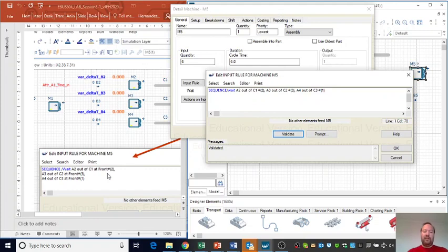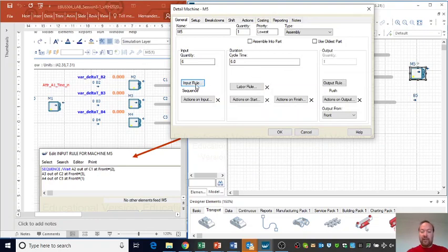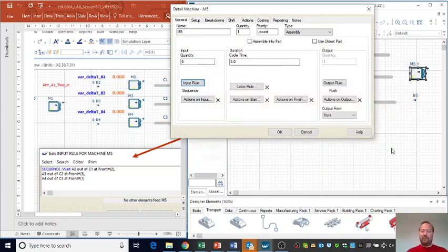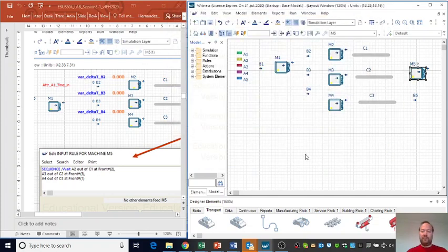Now look, here in this example it says "up front", and I didn't include that. I'm going to click on OK now, and I'm going to see the sequence again. Witness automatically added that, because it assumed that, by the logic, if the part goes from the left to the right and the front is the right, I'm going to take the part from the right. You can say things differently, like if you want to change things from the beginning. You can set different rules. But Witness says that if nothing else is specified, we probably just do that.